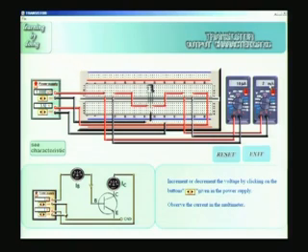3.5 again 2 milliampere. So, you can see beyond 2.5, even if I go up to, let us say, 6 or 7 or 8 volts, you would find the milliammeter shows the same value of IC, which is 2 milliamperes. That is what we saw in the characteristics. Now, let me quickly come back to 0 for the VCC and increase my base current from 10 microamperes to the next value, which is, for example, for 2 volts 20 microamperes.